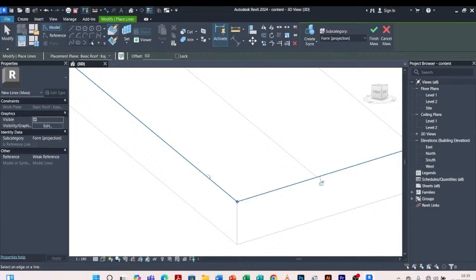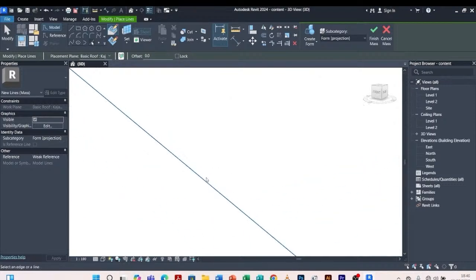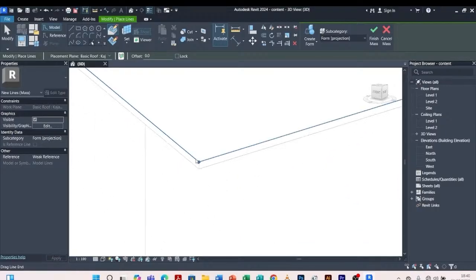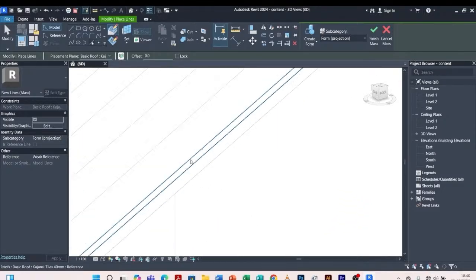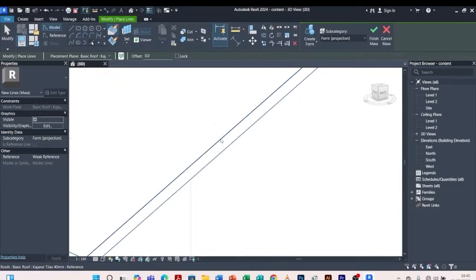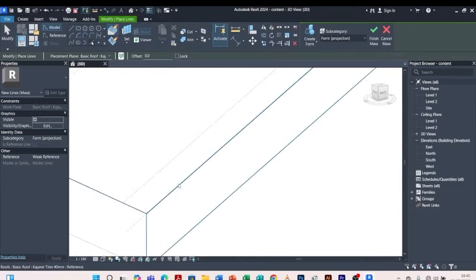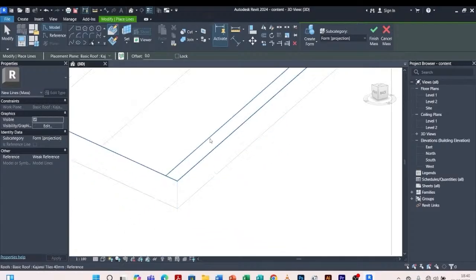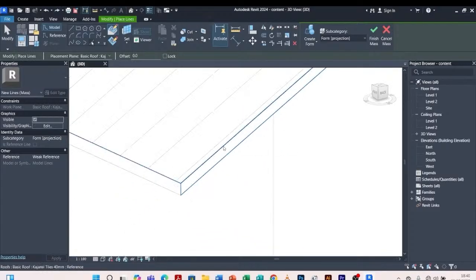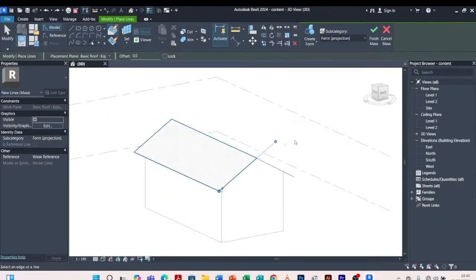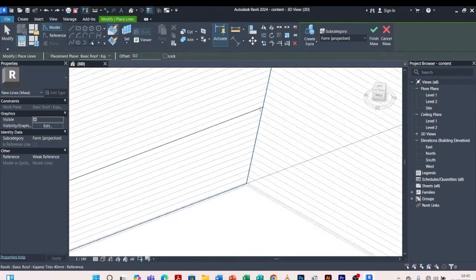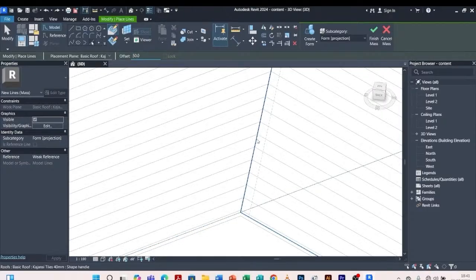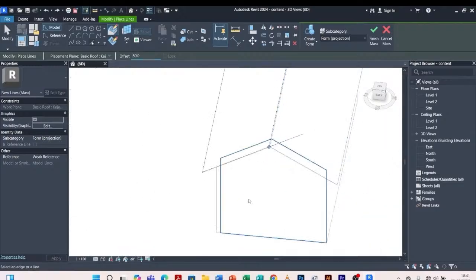So I can go with this first. I click that. I click on that. I come this side also. We are sketching the path. You zoom in properly. You pick this side also. Shall pick that one. Then for this upper side, remember we have our ridge curve passing here. So I'll offset, let me offset 50 on both sides. So I'll offset 50 inwards this side.